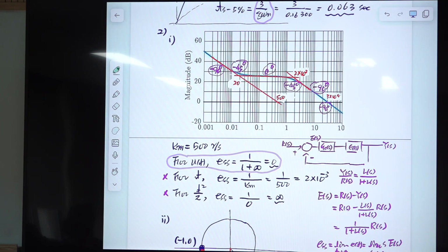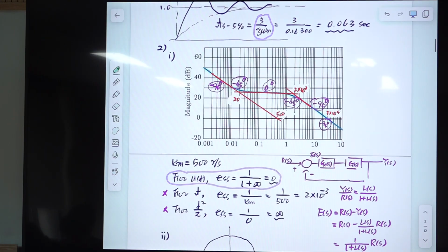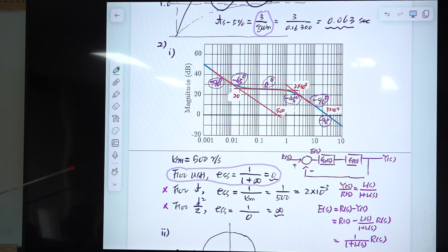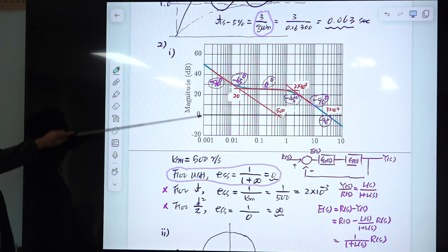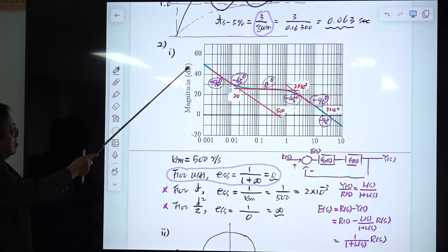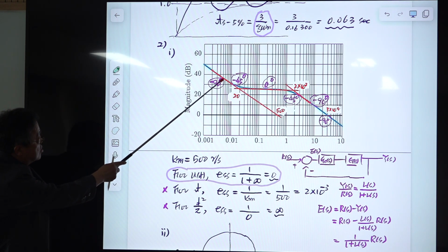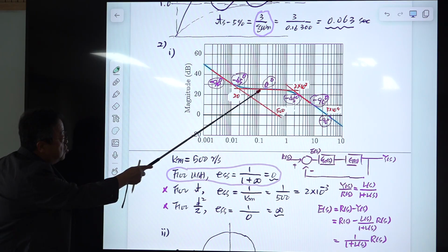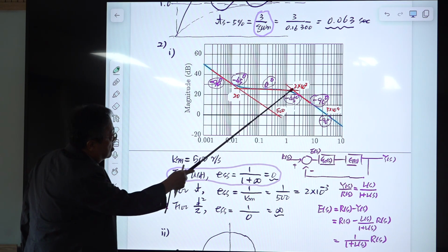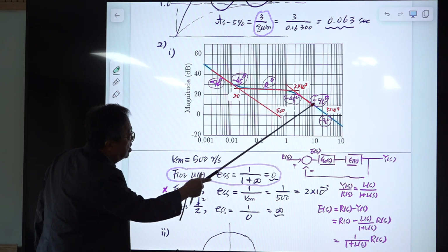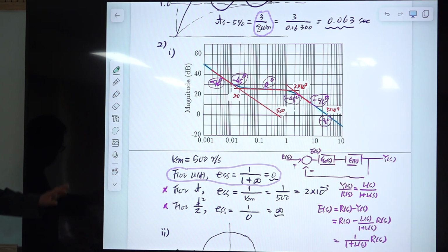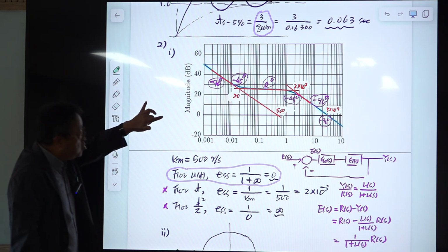If you take the correct approach, okay. And the second Bode plot is shown here. I said this is another loop gain plot of another feedback system. So it starts with this -1 slope, goes to 0 slope, and comes back to this -1 slope. This is the loop gain of some strange system. Usually, you don't want this.